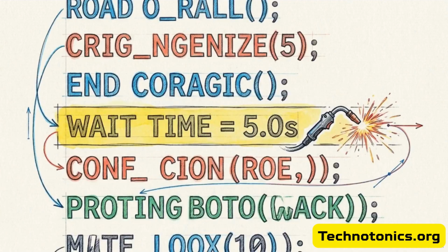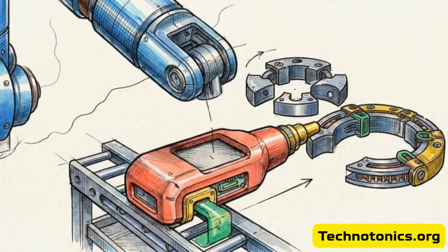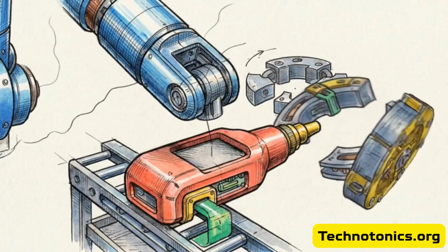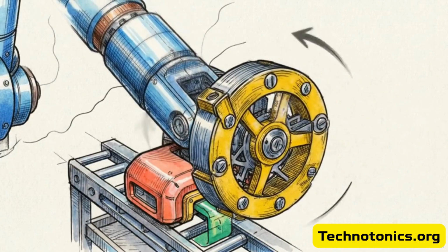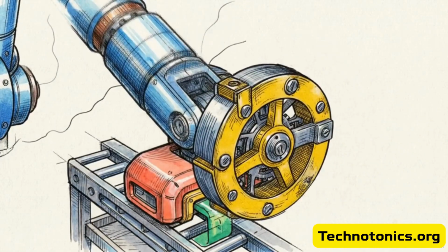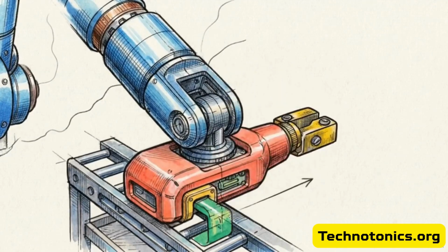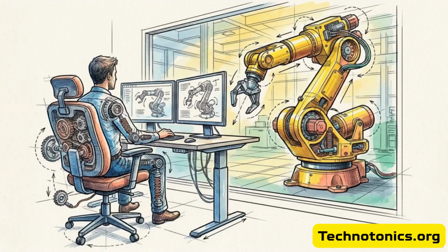We also insert wait commands into the sequence to pause the robot's movement for external physical processes, like allowing time for a welding delay. Next, we embed input and output instructions to trigger hardware changes, such as signaling the machine to swap out a robotic toolhead. Translating complex physical operations into a linear sequence of digital waypoints entirely removes human guesswork from robotic control.